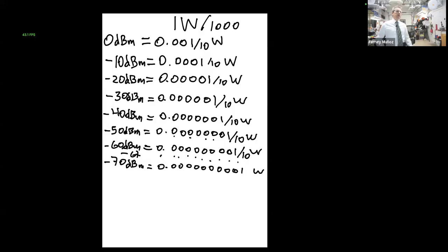When you said minus 67 without any hesitation when I asked, you didn't say, look, well, I designed my networks for 0.0000005 watts. That's what we do. That doesn't sound good. It's complicated. You lose track of all these zeros, and it's simpler to use dBm.